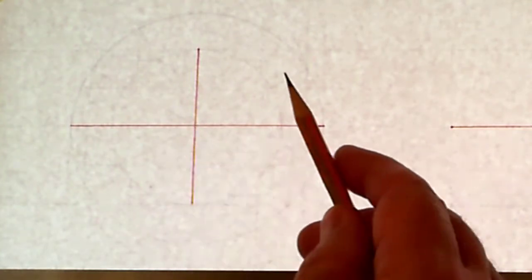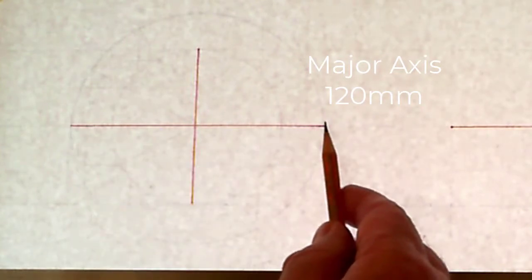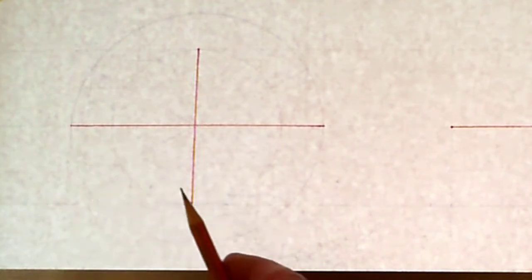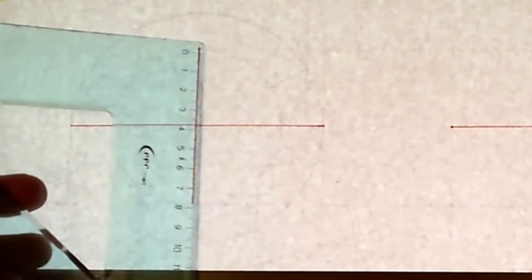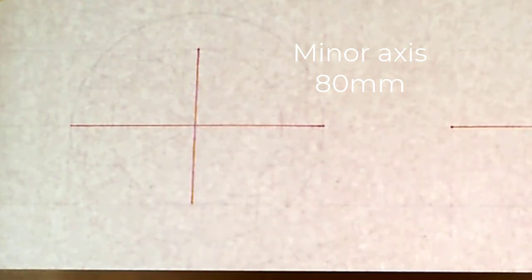The major axis is 120 millimeters, so it's 60 millimeters each side here. And the minor axis is 80 millimeters, so it is 40 millimeters each side here.